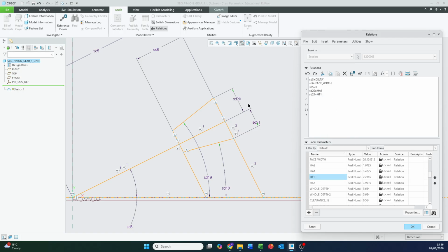Okay. Remember, typically the addendum would be 1 times the module, which would be 3, and the dedendum is 1.25 times the module, which would then be 3.75. Whereas in this case, the addendum is smaller than the dedendum. Just to keep note of these, and it's the opposite value for gear 2. But when you put the two gears together, the clearance on both gears is exactly identical. You can see that by here. The clearance for both is calculated as 0.564 and 0.564 for both.